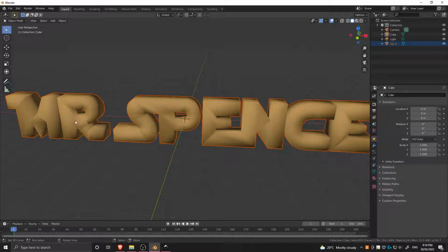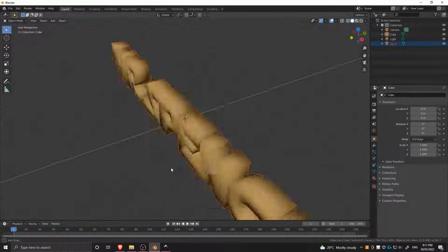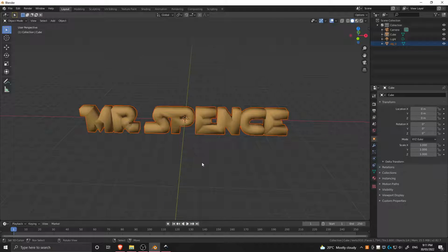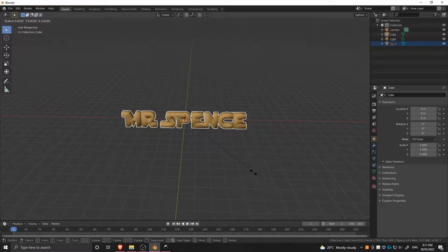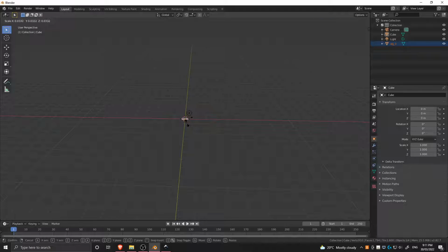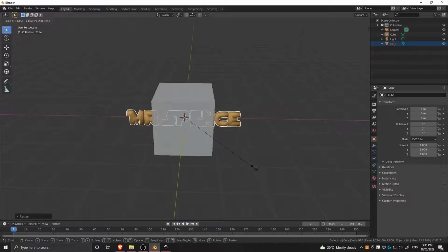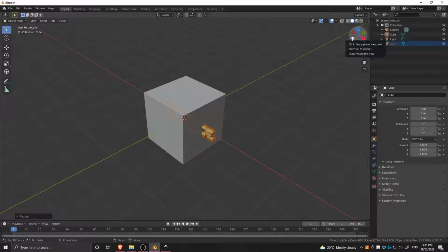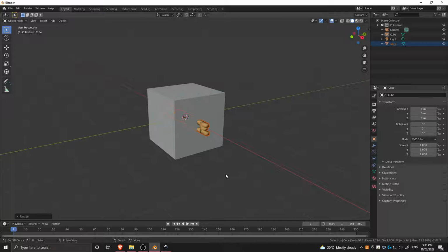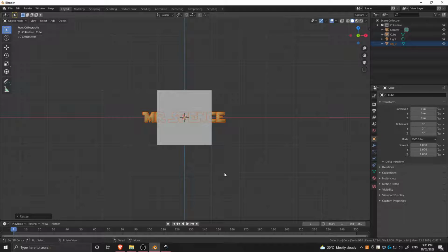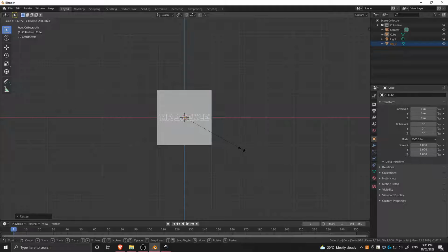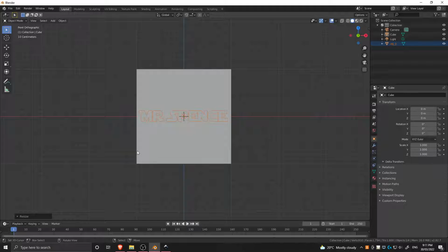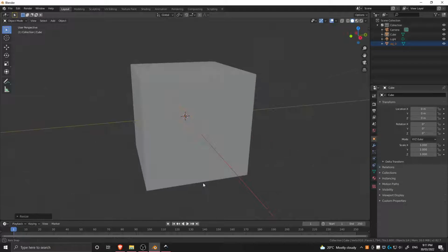Now, because I want to cut this out of that little cube down there, I need to scale this thing way down. So I'm going to hit S for scale, and moving from an outer position closer in, scale it down. Now, it'll be easiest for me if I look in the front, so I can either click on this little green thing here, or I can click 1 and scale it, and I want it to fit wholly inside my cube. Check the sides, not poking out.